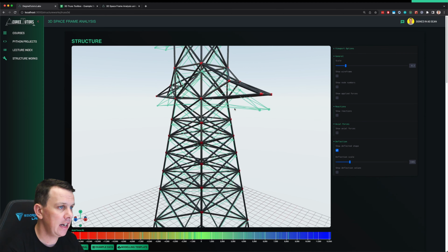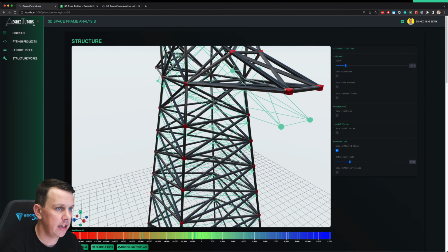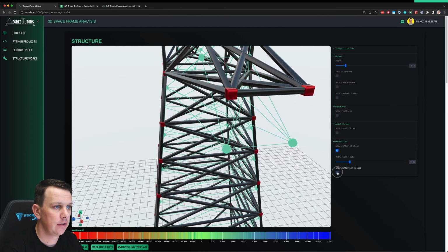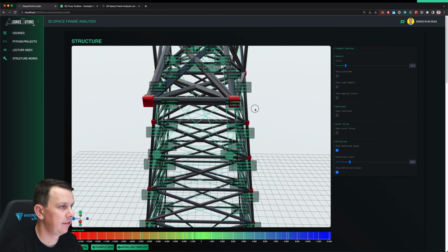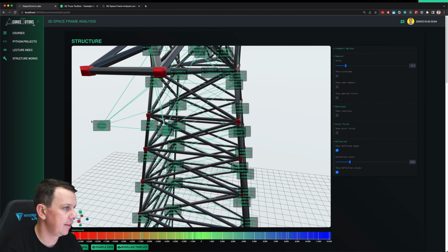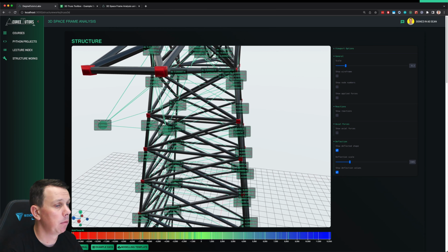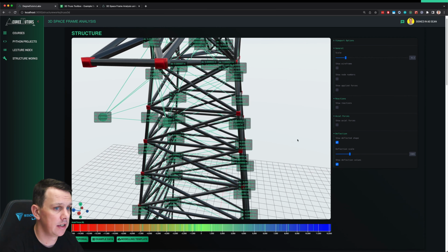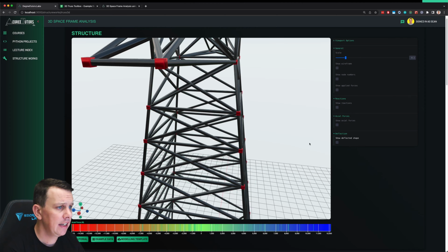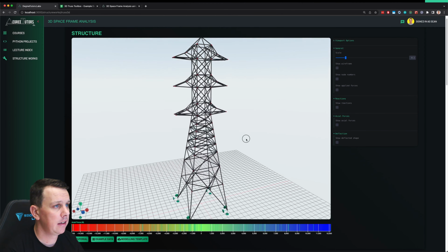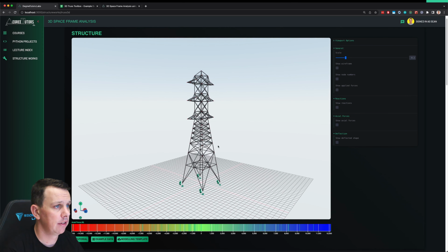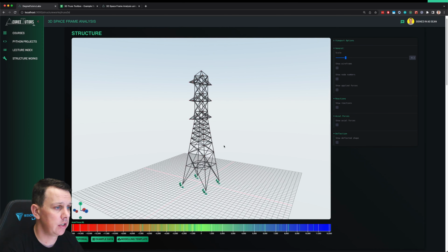And of course, for any of the nodes, the nice shiny red things, we can investigate what the X, Y, and Z deflection is. You go down to the deflected node, and you can determine what the X, Y, and Z deflection of any of your nodes is. All right, so that, in a nutshell, is the 3D truss solver toolbox, just an extension of the 2D toolbox.